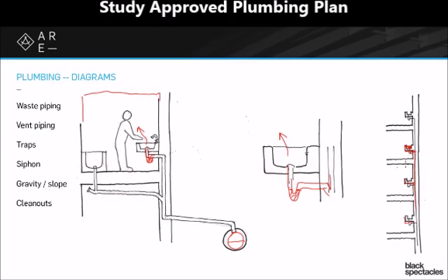And so as it rushes by, it's going to push the air that's in front of it out of the way, and it's going to pull air behind it. Because something is creating a vacuum, something has to reoccupy that space. So if you imagine that water flowing down very quickly down that pipe, as it rushes by and it needs to create that vacuum, it has to pull some air in to fill that space, that void in the pipe.